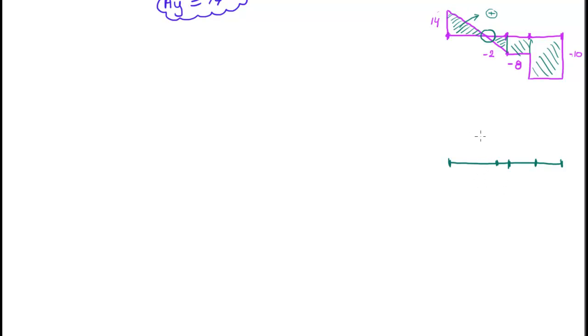Okay, so as I promised you, if we calculate the areas under the shear diagram, we should get some values here. The value at this point is the value of the area under the shear diagram for the whole shear diagram before that point. What about at this point, which corresponds to this one right here? The value of this area plus the value of this area will give me the value of the moment at that point. What about this one? It's the value of that area plus that area plus that area, and if I sum them, I'll get the value of the moment diagram at this point. Keep in mind, the area on top is positive, and all the values of the areas here are negative.